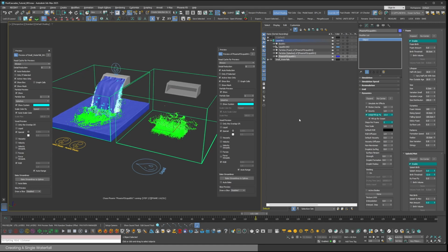It looks like the foam appears at the bottom, where the liquid hits the ocean surface. The foam generation threshold uses a slightly different algorithm than the one for the splashes. It is set in centimeters and measures the difference in the velocity inside each voxel compared to the velocity in its neighboring voxels. 5 foam bubbles are created inside that voxel if the difference is bigger than the threshold value.